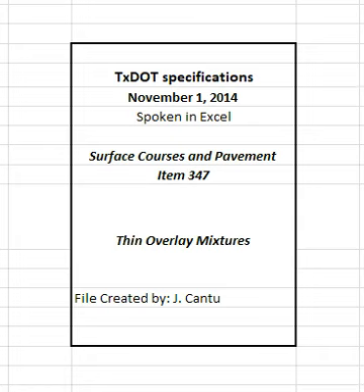4.9.3.1.2 Irregularities. Identify and correct irregularities including segregation, rutting, raveling, flushing, fat spots, mat slippage, irregular color, irregular texture, roller marks, tears, gouges, streaks, uncoated aggregate particles, or broken aggregate particles. The engineer may also identify irregularities, and in such cases, the engineer will promptly notify the contractor.